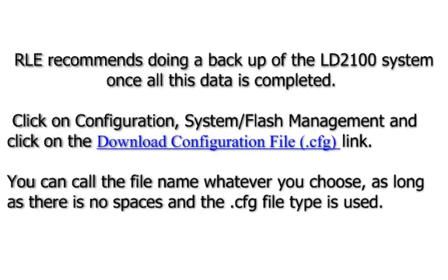RLE recommends doing a backup of the LD2100 system once all this data is completed. Click on Configuration, System Flash Management, and click on the Download Configuration File .cfg link. You can call the file name whatever you choose, as long as there's no spaces and the .cfg file type is used.